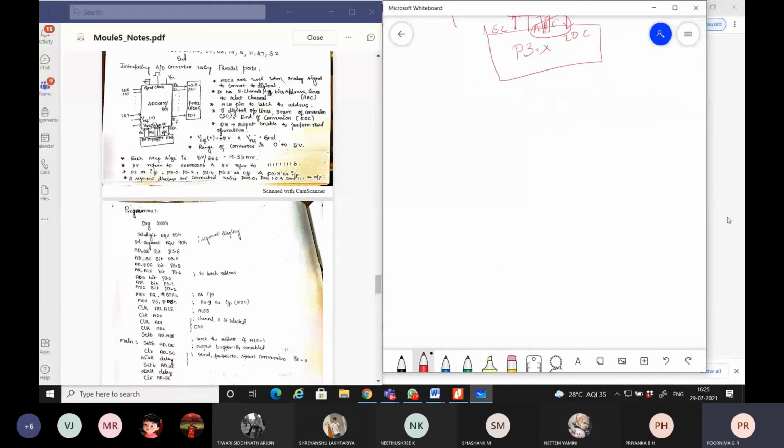So where will these ADCs be used? They will be used only when an analog signal is to be converted into digital. The ADC we have chosen is an 8-channel ADC which has 3 address lines to select the appropriate input channel, and then there is an ALE signal too.